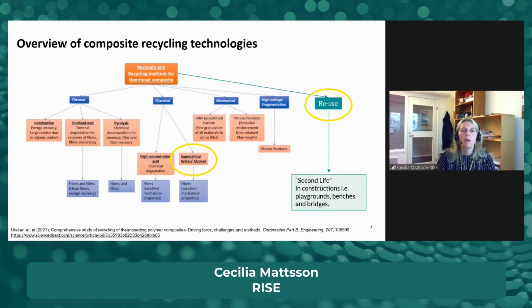So here is an overview of existing recycling technologies. And in my project at RISE, we focused on the new technology, chemical recycling, and we specifically worked with subcritical water, so-called solvolysis or HTL. But we realized it's really hard to release the glass fiber from these dense structures.